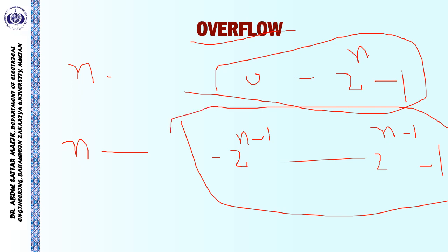After performing the addition or subtraction of two numbers, the question is whether the result is within the range of n-bit numbers or whether an extra bit is generated. If the two numbers are unsigned, that extra bit is indicated by the carry bit. And as we mentioned in the previous slide, if the two numbers are signed numbers, the result will be indicated by an overflow bit.